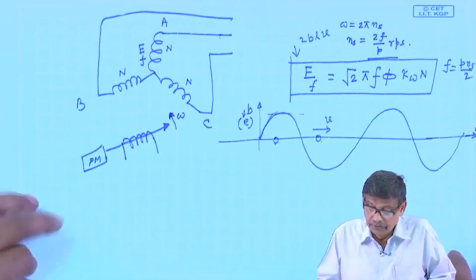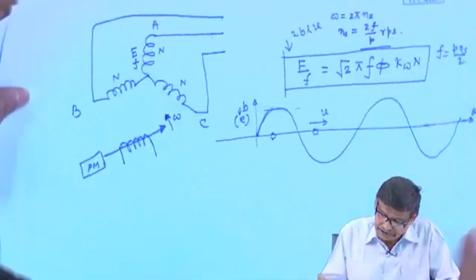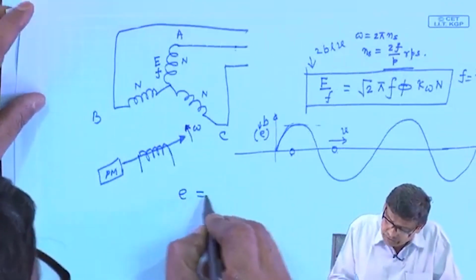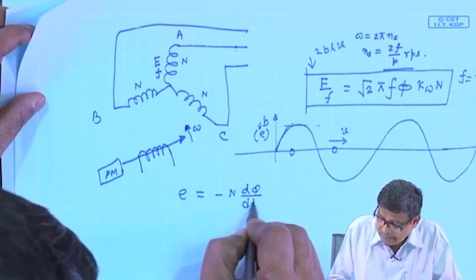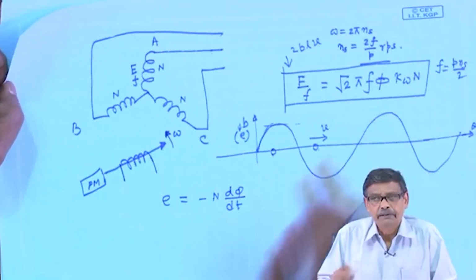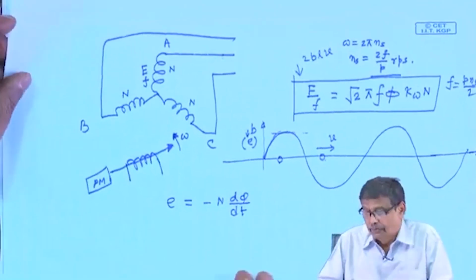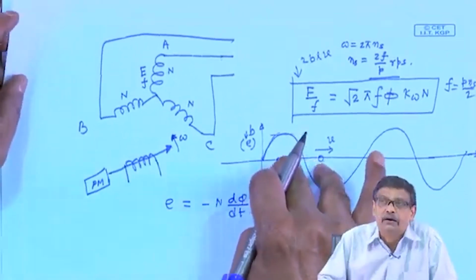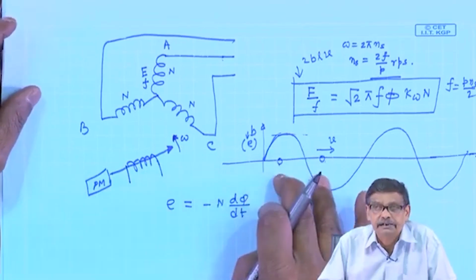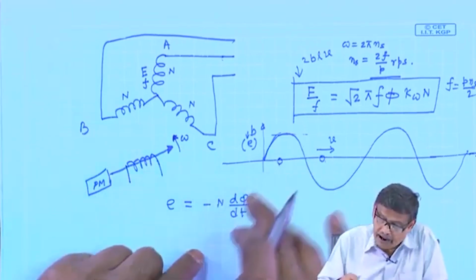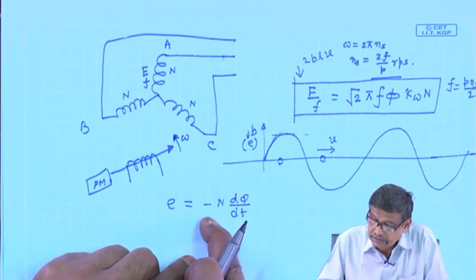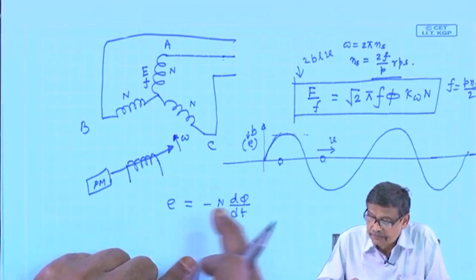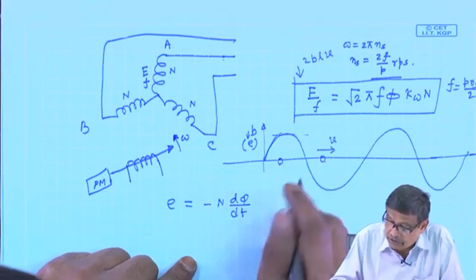Now, what I will do is go by Faraday's law, that is, induced voltage, which I also knew, is equal to minus n d phi dt. So, I start with B, calculate the flux linkage with the coil at a given time t, and differentiate it, take the negative of that to get the instantaneous value of the induced voltage across the coil. What is this coil?